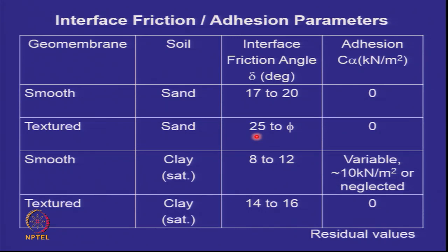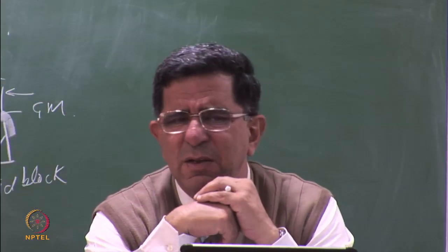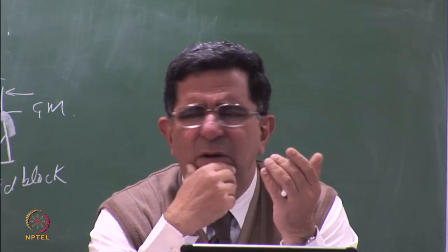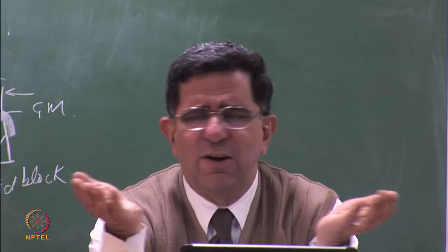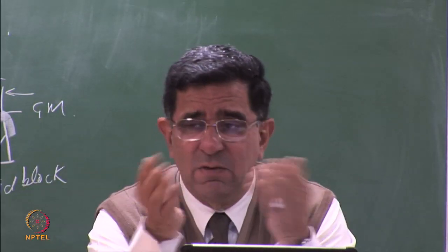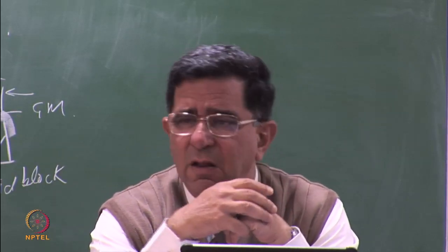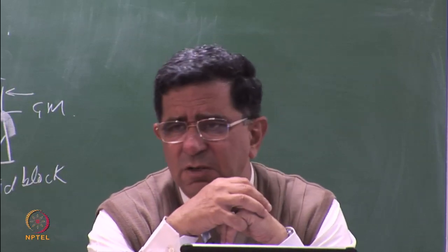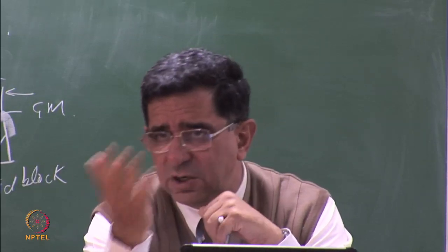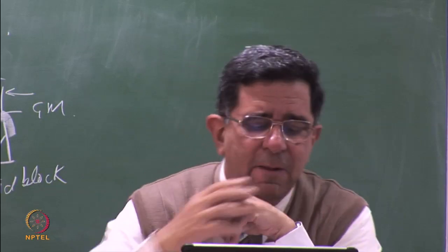Like a typical designer, even I, when I have designed some of these facilities in India, on all the slopes, whether in the liner or in the cover, we have been using textured geomembranes. But at the base, do we need a textured geomembrane? Not really, because there's nothing going to slide on a base. This is what we thought till we really did an analysis recently. So we have been using smooth geomembranes on the bases. Cost is not much. It's a 10-15% cost difference between textured and smooth geomembrane.